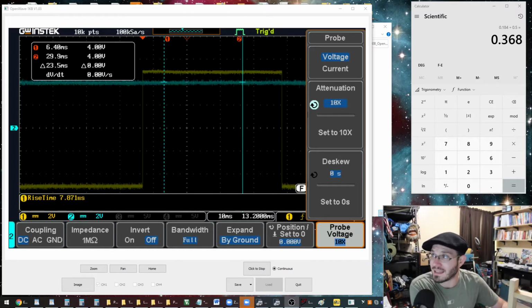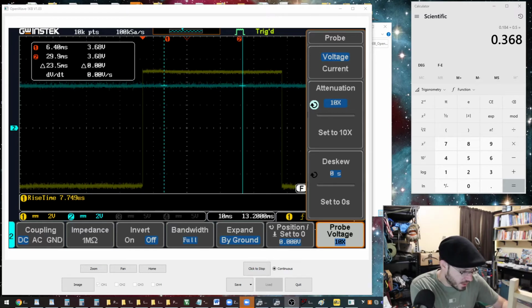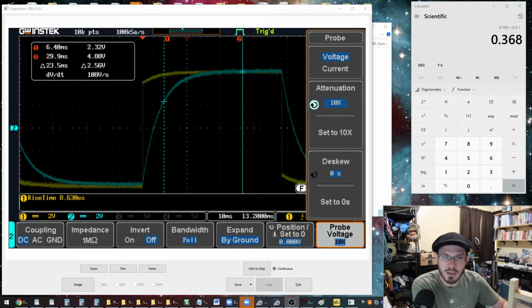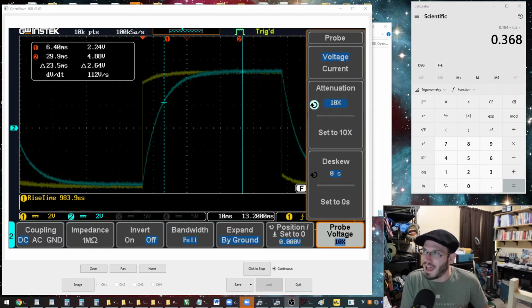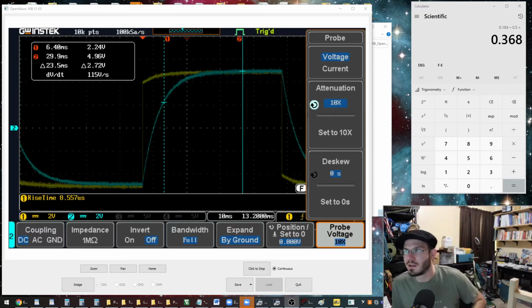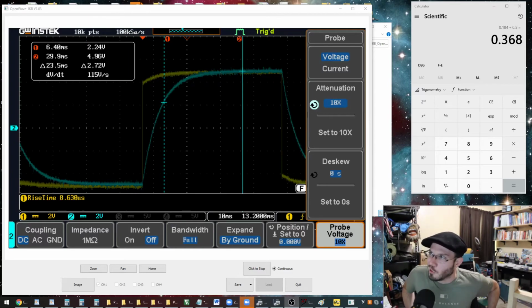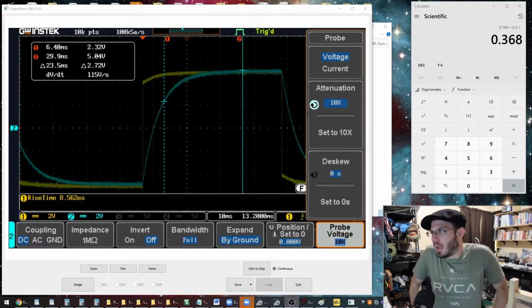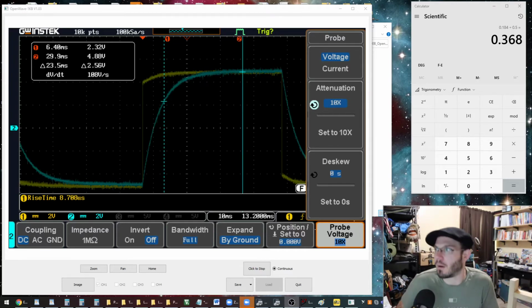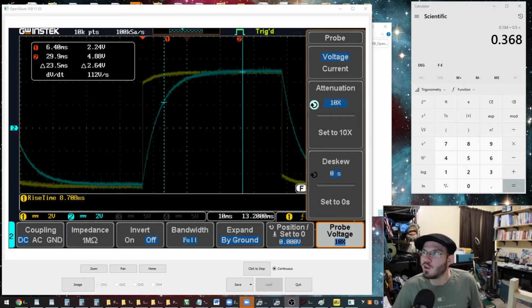My function generator has to act like a power supply at this point. So when the cap is being charged, at time 0, there's quite a bit of current. And so my function generator is having a little bit of a hard time keeping up with that current demand. So that capacitor is really kind of loading down that circuit initially at time 0. Okay, but that's okay. For all practical purposes, this is going to give us the answers that we want to see anyways.